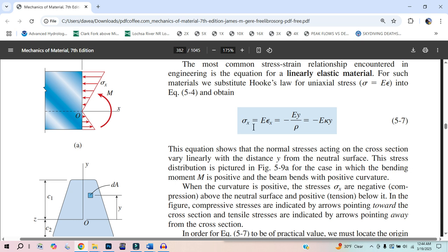So if you don't like the word stress and strain in this number, just say, hey, this is the load, this is the change in length. Obviously this load has to be on a material that has some sort of area, whether you're pulling on its surface area. And this change in length, well, you had to start with an original length of something, and then you changed it to a new length. So this is a percentage of that change in length. It's a proportional change in length. And then those two terms now are kind of universal.